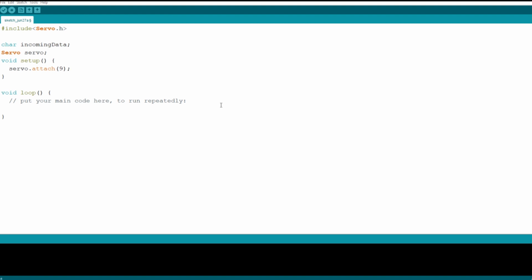And of course, let's start the serial communication since we will communicate over the serial port. So for this, let's move to a new line and call here Serial.begin. As you know, we need to enter one parameter here, which is our baud rate speed. When we completed our Python code, we defined our serial port baud rate speed as 9600. So let's define 9600 here and put a semicolon. And finally, let's move to a new line.